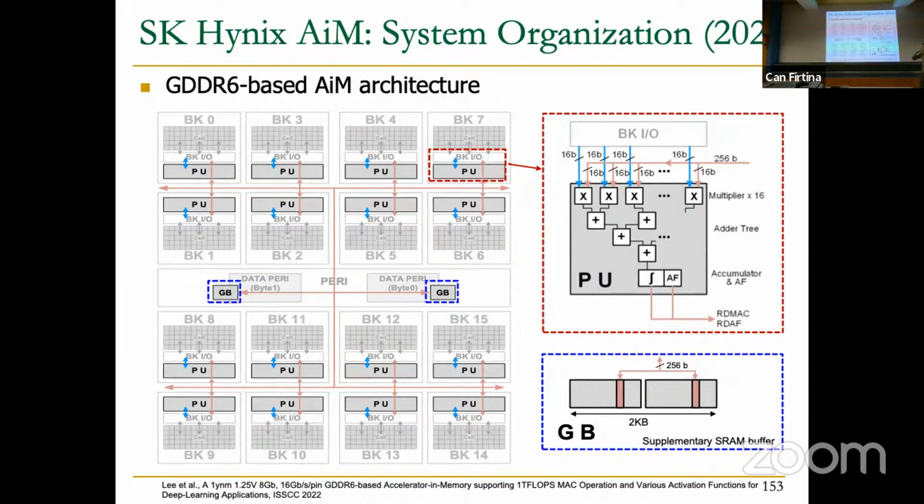And they even have a few innovations that I like a lot. For example, some interpolation function, and also a way of obtaining values for activation functions. You might know that many DNN layers have some activation function at the end, things like sigmoid or ReLU or GELU or other types of activation functions. These sometimes require very specialized units. Sigmoid, for example, is an exponentiation, right? And as you see, there is no unit to perform exponentiation there.